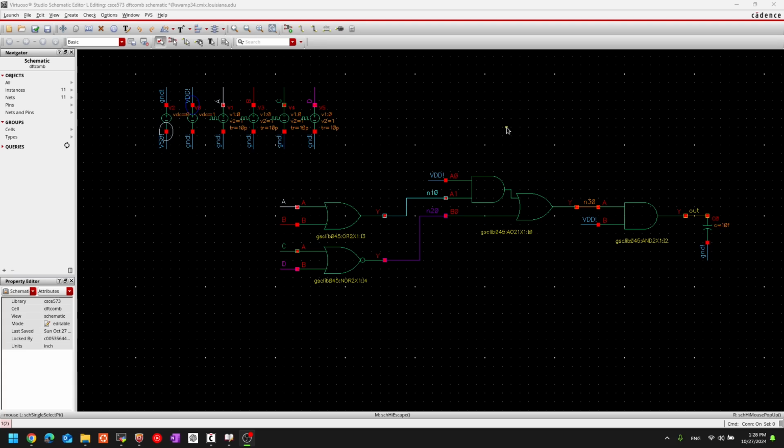And you built the circuit yourself, and you named every node correspondingly. I really recommend that you name the nodes in between as n and with an index. So n10, n20, n30 are the intermediate nodes that I named here. I connected VDD to some of these inputs, and I have input pulse voltage sources connected to the input of this combinational circuit.